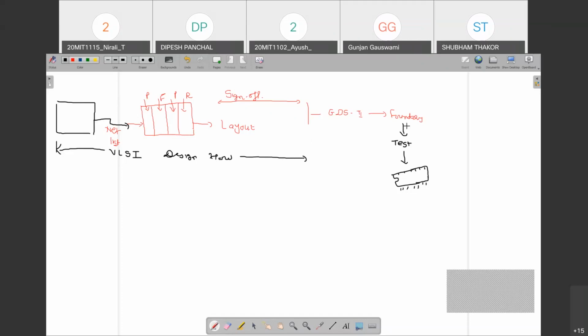So foundry people really rely on this VLSI design flow, to avoid getting an unexpected output. So we are going to discuss checkpoints first, or the sign off mechanism, and then we'll see what the initial steps are. So first checkpoint: once your tentative layout is ready, it is checked with the very first and very important one, that is called the DRC checkpoint.